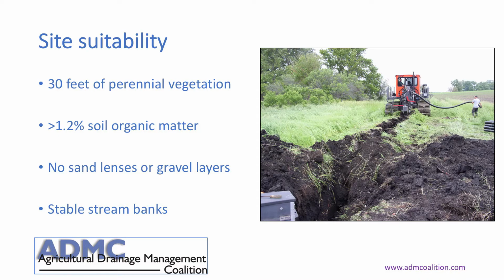So saturated buffers, if we ever go out on a site visit for somebody that's interested in one of these tile treatment options, usually saturated buffers are the first option we like to consider. They are a little bit more site-specific than the bioreactor, which is more of a generalist type practice. Like I said, bioreactors can fit just about anywhere.